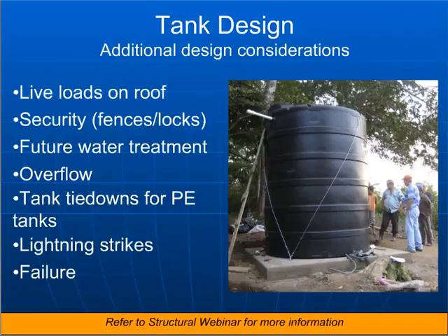But again, just make sure that any coatings that do go inside of the tank are actually approved for potable water applications. Don't just settle for the paint can that somebody recommends at the hardware store. Make sure that it is in fact a product that can be used for sealing water tanks.